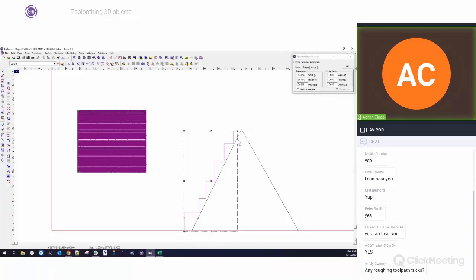You can do a 1/4 inch with a 1/4 inch. So you can 1/4 inch end mill, hog out all the material, then come back with a 1/4 inch ball nose, and then cut it this way. And so that works well. That's how you would set up a rough cut inside of EnRoute with your 3D.